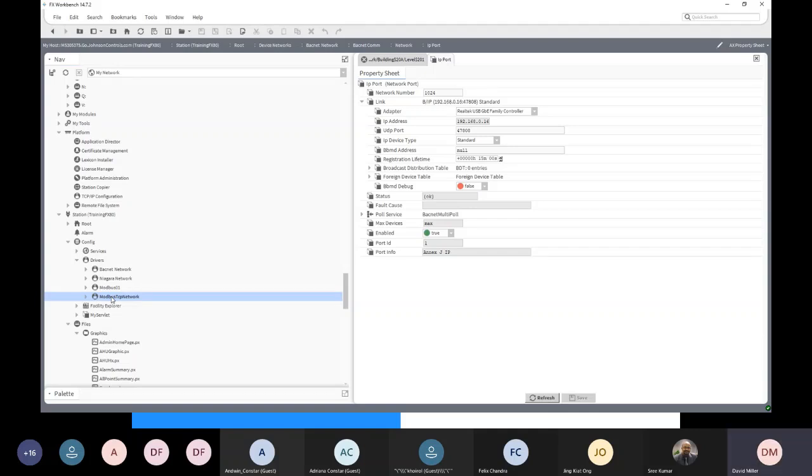Okay, if all you're connecting to is FX80s, then all you need is the Niagara license to cover that. If those FX80s are going out and connecting to Modbus or BACnet, IP or RTU or MSTP, it doesn't matter what the FX80 is doing. When it talks back to the server, it's a single Niagara connection and it's covered by the server.